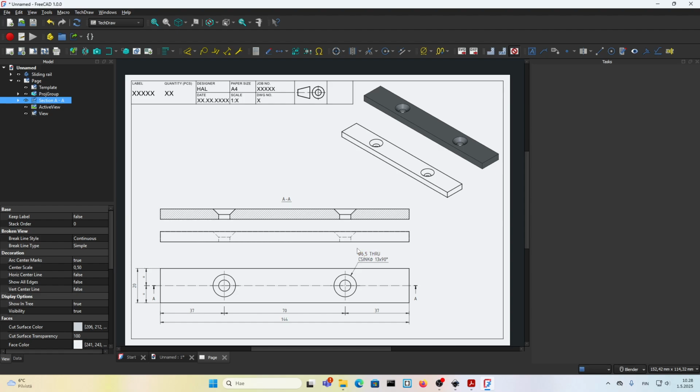It happened once in my workplace, where the diameter was drawn as 18 and it was written in here 22, and that created a big problem. The part was very expensive. So to avoid these kinds of mistakes, always model them correctly. If it's 6.5, model it 6.5.